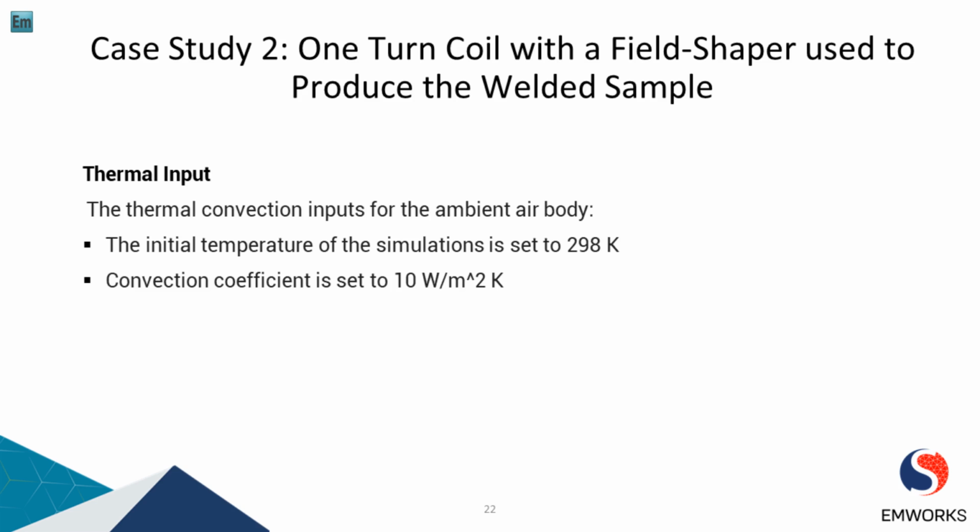To ensure that the thermal effects are accurately taken into account, we need to have a parameterization analysis and see the influence on the behavior of the materials during the welding process at different initial temperatures or at different convection coefficients.